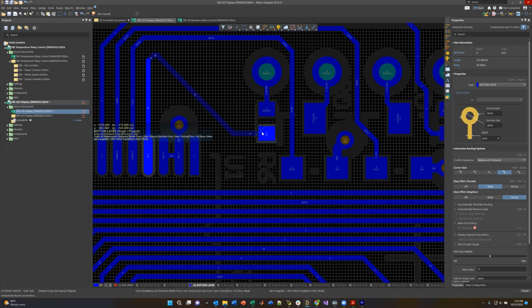This here is the actual part itself. So common is over here, and there's your 2 switch contacts, and these 2 contact points here are the actual coil that we're engaging. So you put current through here, and it turns on and off the relay. This here is the 5-volt power supply, the LM2595, the fuse. Here's the main connector we looked at earlier.